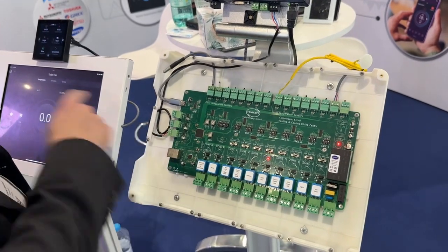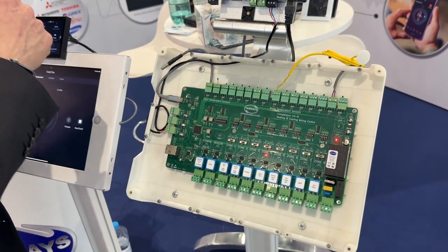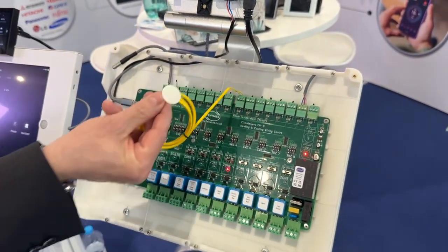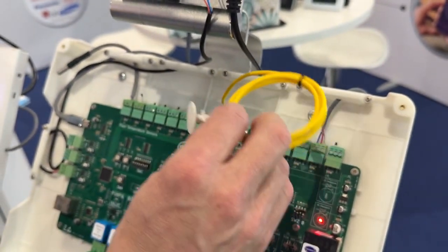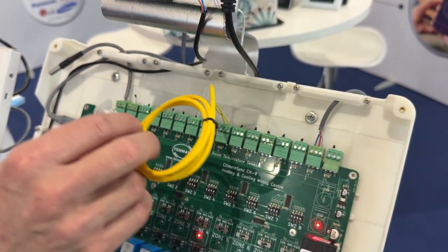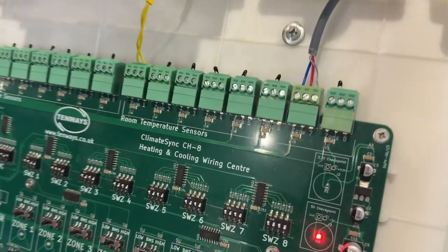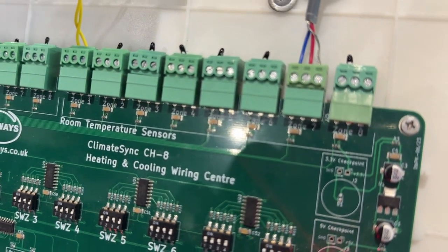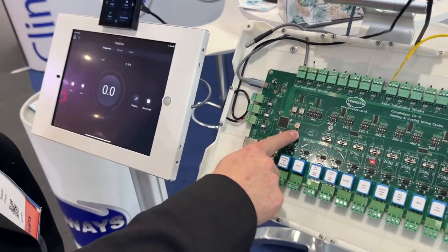You can have some local Modbus controllers, and from this side we'll be talking back into the air conditioning, which means that when we use one zone sensor, which could be any type of NTC as we said, that zone sensor is going to feed the room temperature into the air conditioning, which means the air conditioning will continue doing its own inverter or VRV, VRF logic while looking at our sensor. And all that will integrate seamlessly into Control4 with addressing on the board.